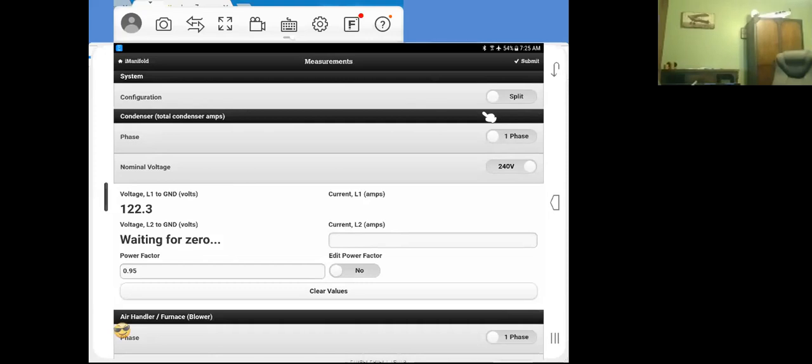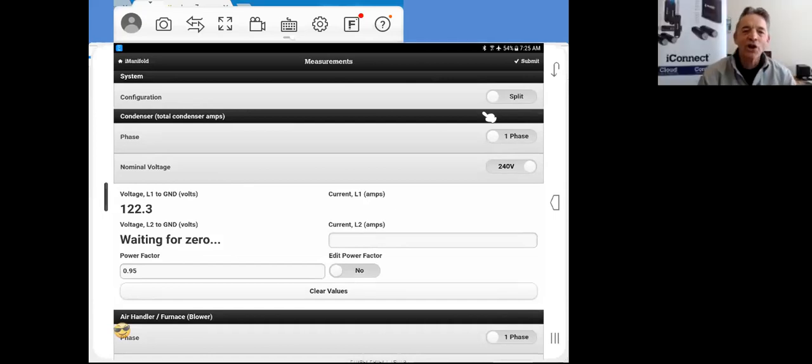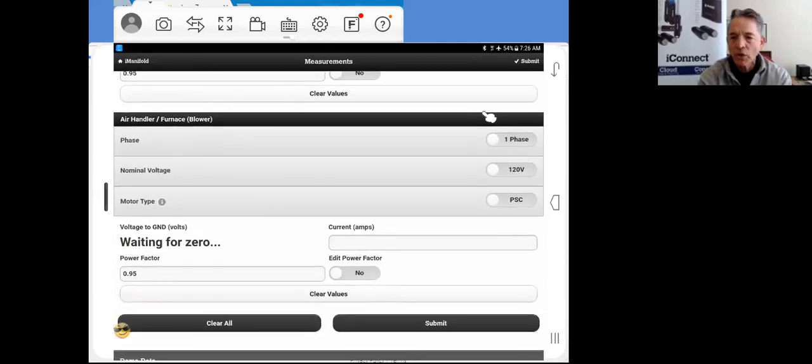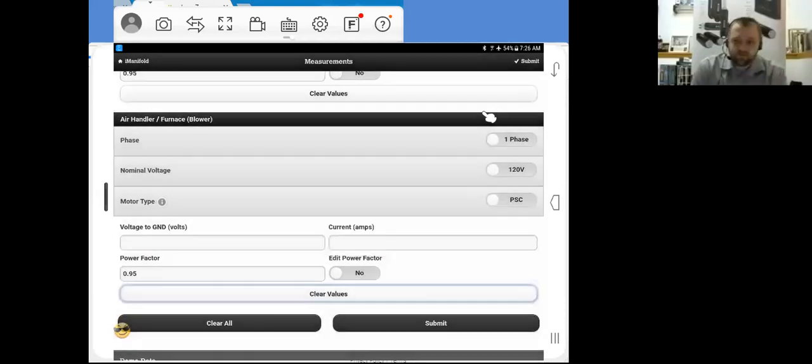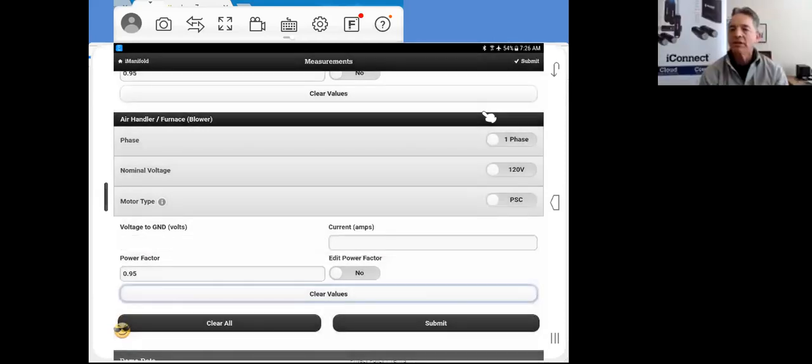What are you talking about, a wrestling match? Earl just asked about what the difference was between the redfish meter and the UEI meter. And mainly the difference is with the UEI meter, we get streaming of amps and volts simultaneously. And that's the thing that we were excited about, because at that point, we can truly do live data logging instead of just taking a snapshot of the system right then and there.